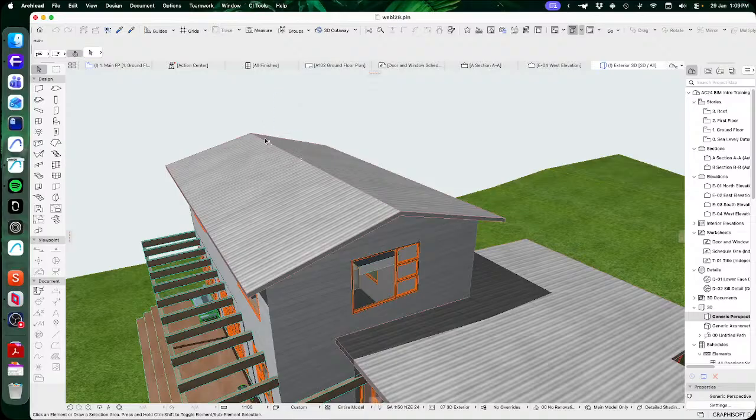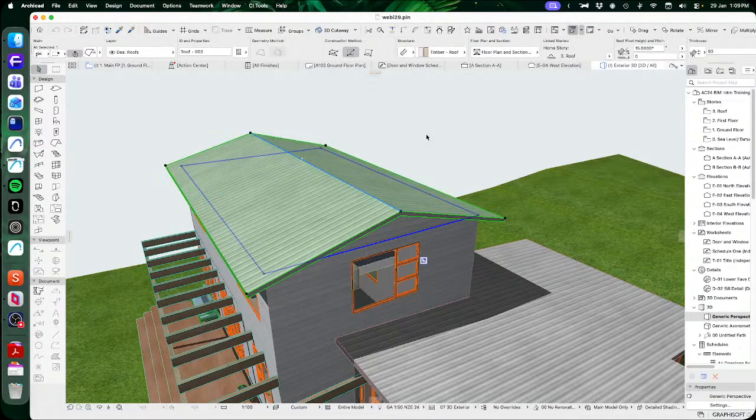So we have a system called styles, which is in both the wall and roof coverings, and it allows you to create sort of preset styles, which is why they're called that, of covering that you can then easily apply to other wall and roof coverings in your projects, and you can export into other projects so that you can use the same types of thing everywhere. So if you create some sort of cladding presets that you think you'll use quite often, you can save those as styles and then use them across all your projects.